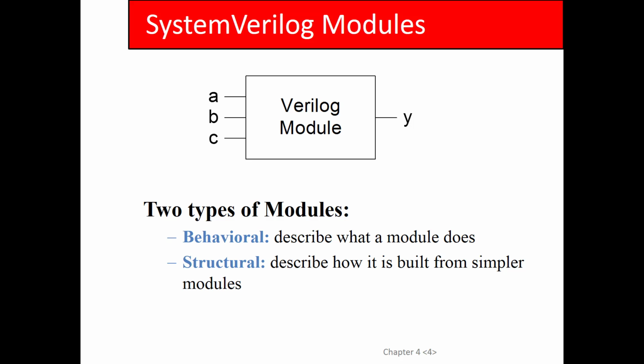Most code you write in Verilog is structural. Probably 90 to 99% of it. You very rarely are writing behavioral code in most cases, because behavioral code is when you're at the leaves, when you're designing the low levels. But once you've got a basic library of components built up, at that point you're just assembling them together, and that's structural code. So most of the time you spend is in structural code.